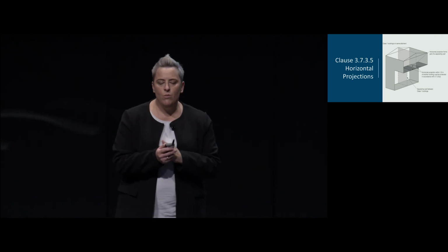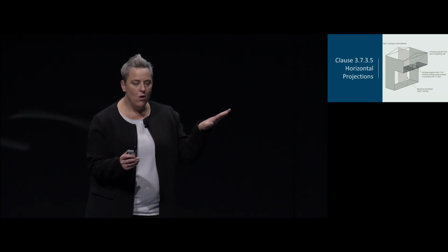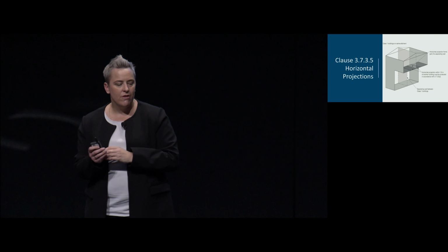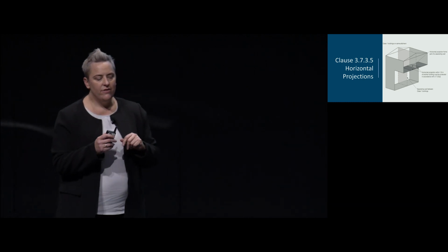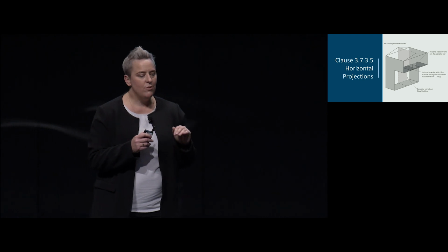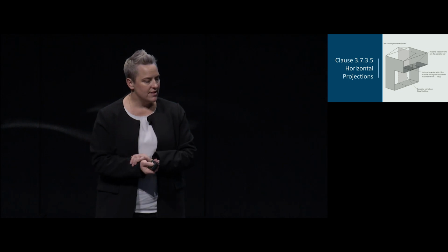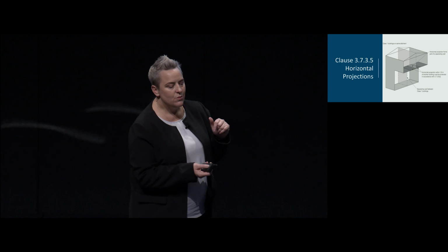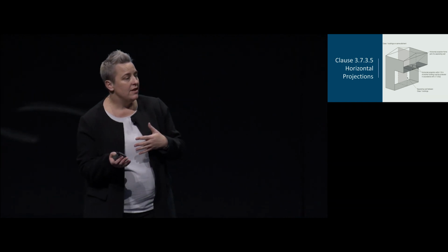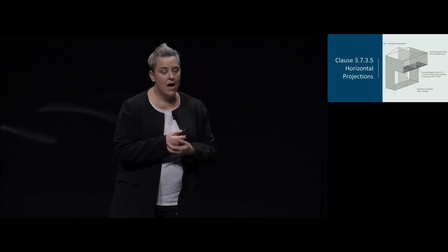So it's becoming more and more common for your Class 1 building that incorporates a cantilevered floor, as shown in the picture on the screen. So in the 2016 NCC, in the deemed to satisfy provisions, would require a separating wall to commence from the footings or the ground slabs. So in a cantilevered situation where two Class 1 buildings are required separation, this couldn't be achieved without a performance solution or going down the modification path.